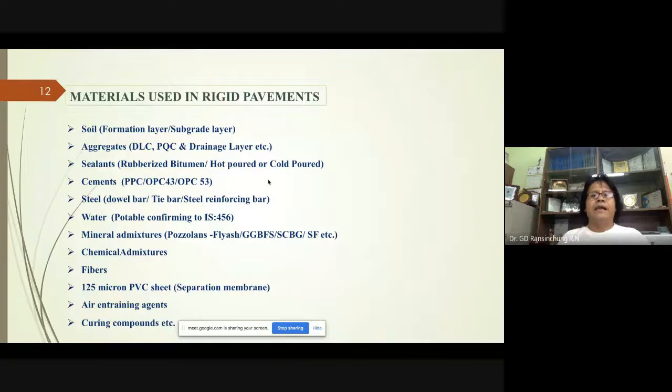This kind of table is provided only for those projects where the design facilities are very challenging, and if they are not able to carry out the design scientifically at their end, in such circumstances, in the worst case, they may refer to these guidelines. Otherwise, ideally the dowel bars and tie bars are to be designed for the given traffic load, as well as for the different grades of concrete used.